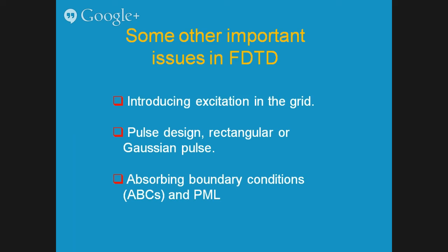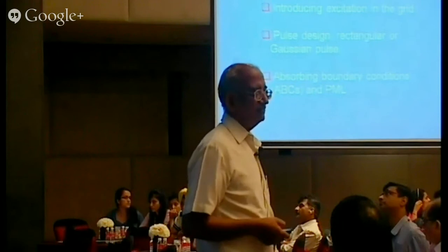Yeah, monocycles are also used. We are now talking about the absorbing boundary conditions. Absorbing boundary conditions are a part of any numerical computational technique. So we can put it in terms of either a differential equation, or we can put it in terms of PML, perfectly matched layer.